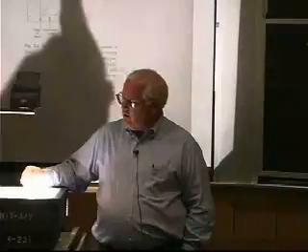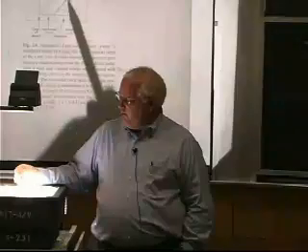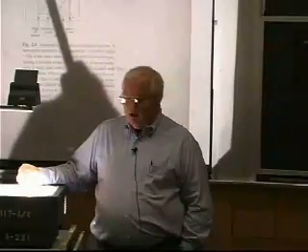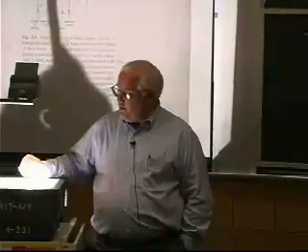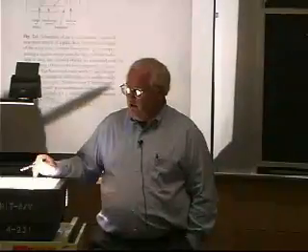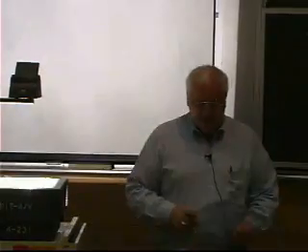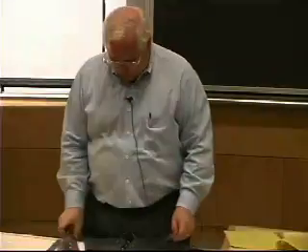If your crack is oriented through the projection, you'll get a very high intensity. If it's a lamination, you may not pick it up at all. But if the stress is in that direction, that is critical for that type of flat lamination, you'd better do an X-ray from that direction too. So it's orientation dependent. It doesn't tell you everything as far as that goes.